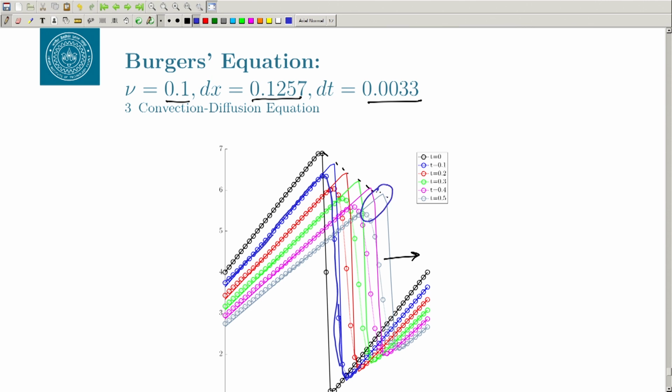Okay. Here you can see this is the peak in the analytical solution, and this is the peak that you are getting in the numerical solution, and similar behavior you would see downstream also. Okay. If you improve the grid size, make it finer, it will become better, but regardless of that you will have certain numerical diffusion that you cannot avoid.